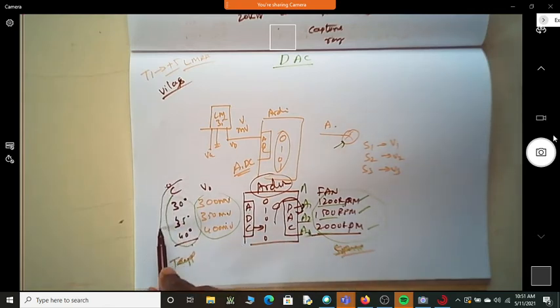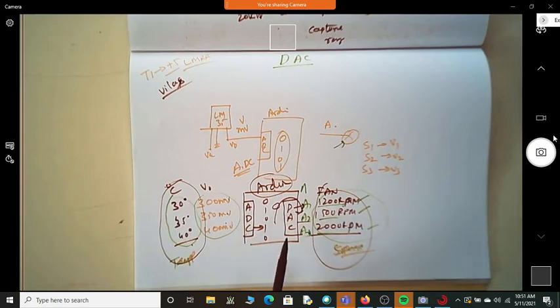So for any control of a physical parameter to control the other physical parameter, ADCs and DACs are a must if you want to interface to any digital controller. If you have any microcontroller, if you want to control any physical parameter, you need one ADC to convert analog to digital, and using digital you can handle the parameters very efficiently in your controllers. You do the manipulation using digital values, and if you want to again give the analog output to your external world, you use a DAC, that is digital to analog converter, so that these analog voltages can change the physical parameter on the actuator side.